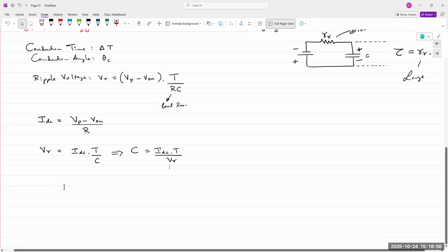So what I'm saying is the size of the capacitor or the size of the ripple does not matter as much. You can attach a Zener diode at the output of a bridge rectifier, and we can obtain a flat line. This is an experiment that is not in 346, but it's a procedure that non-EE students do in their electronics class. They do a bridge rectifier, they do a Zener, and they join them together and get an output. So that's actually pretty cool.